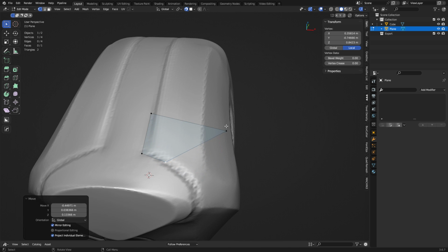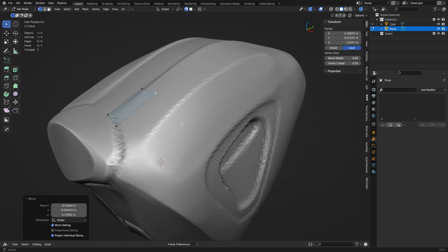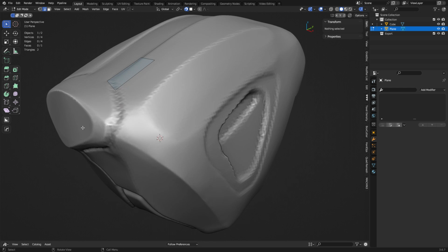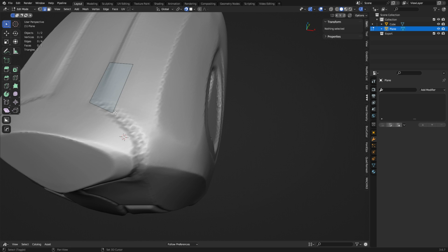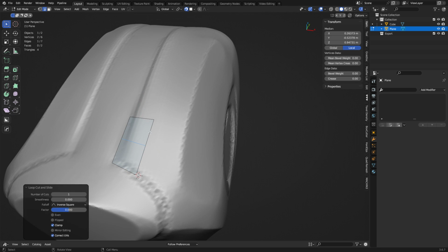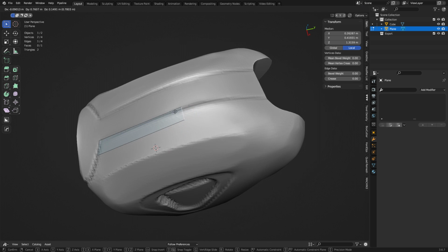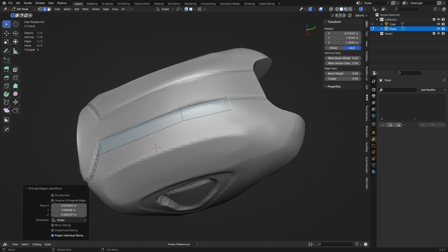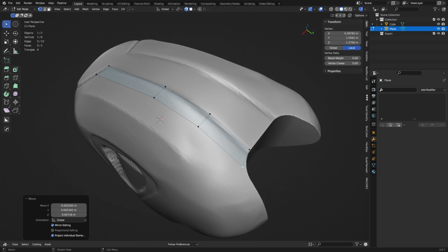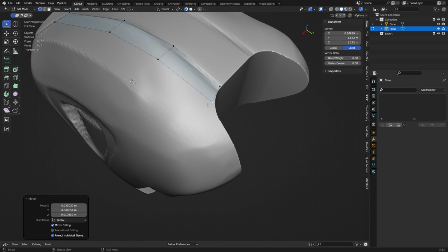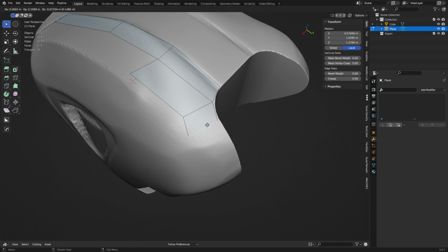And this is view dependent. So if you have, for example, a mesh that runs around as a loop all the way around the model, you select that whole loop and move it. And the moment you move it, it's all going to shift over and snap to this front side here. Don't do that, okay? It's a big problem. But you can keep these things relatively simple at first. And just go for big shapes first. Just start knocking it out and hammering it out, basically. So you can see here, this one I want to shift that way, and then I want to go like